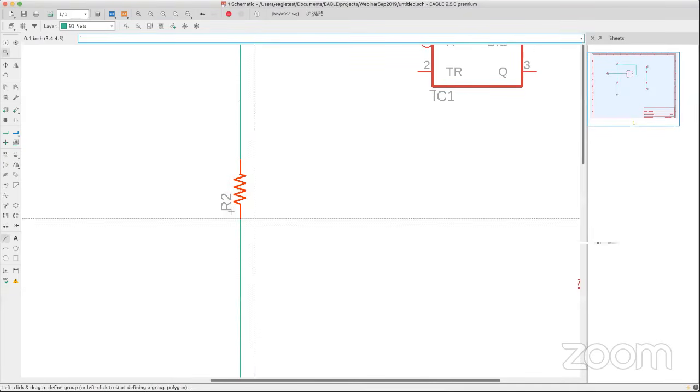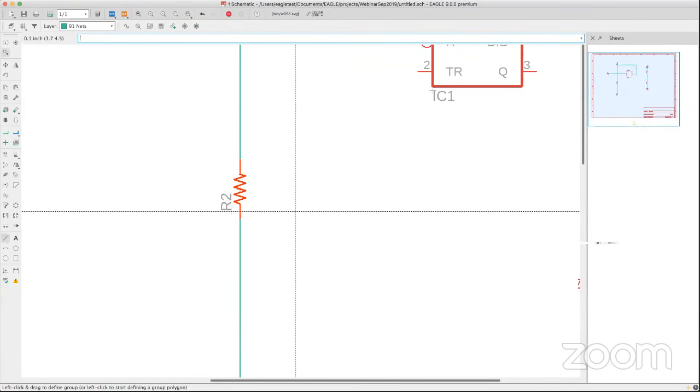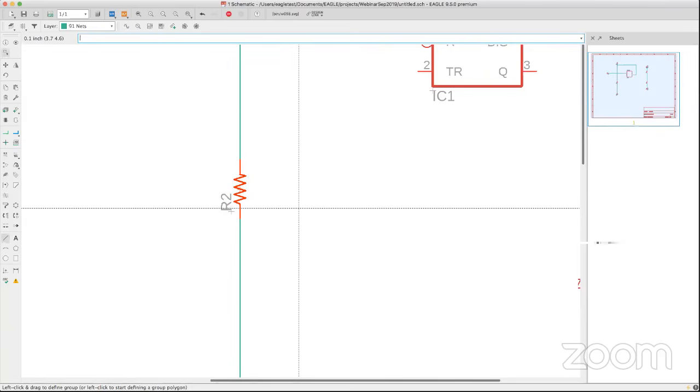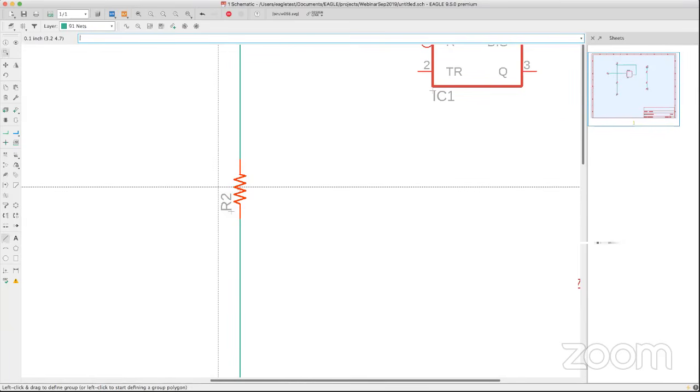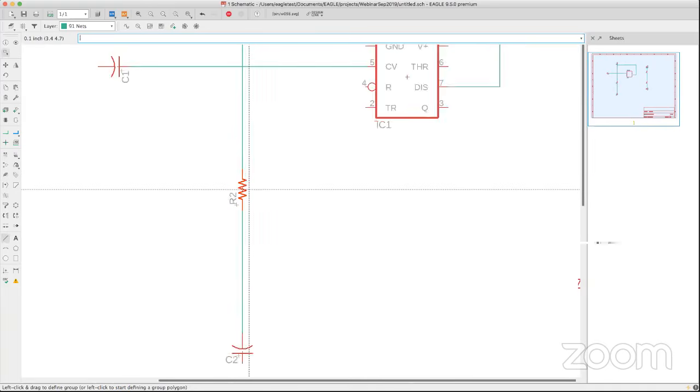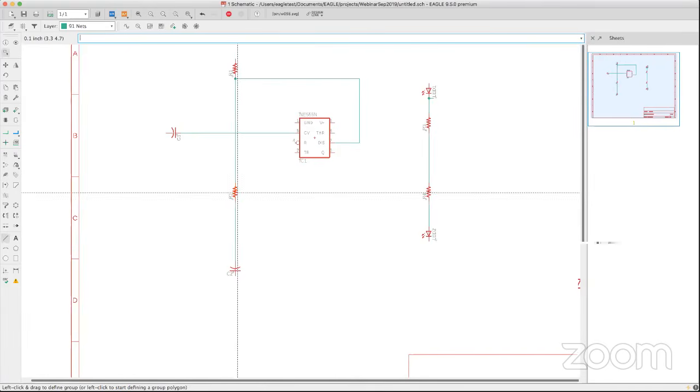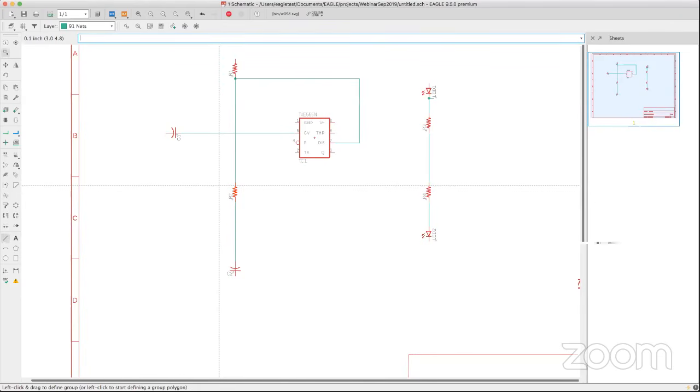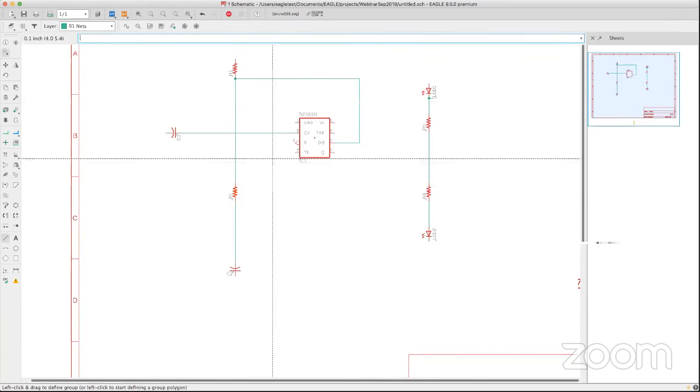So you don't have to delete the connection if you just want to add a component to an existing connection. There's no need to delete them. You could just drag, or just add the part right there where that net is. It will split the names of the net and make that a member of that net. Okay, just wanted to give you that. We'll be doing more of those in our next tip webinar that we plan to be hosting really soon.